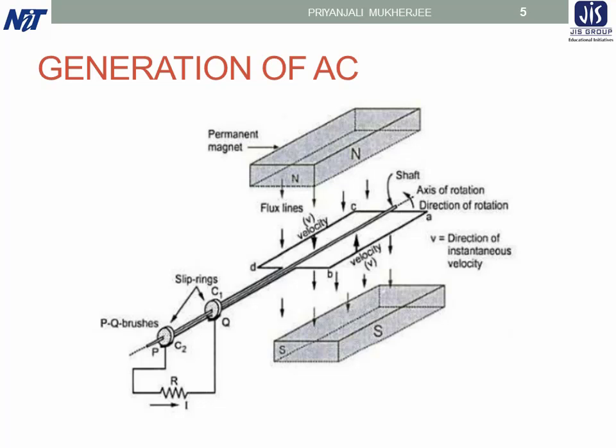In fact, there are certain types of work for which alternating current is unsuitable and direct current is absolutely necessary, such as electroplating, production of industrial gases, electrotyping, refining of copper, storage batteries, municipal traction, etc. In some power applications, the AC motor is unsatisfactory, for metal rolling mills, paper making machines, etc. The direct current required for these applications is nowadays derived from an AC supply by the use of suitable converters and rectifiers.